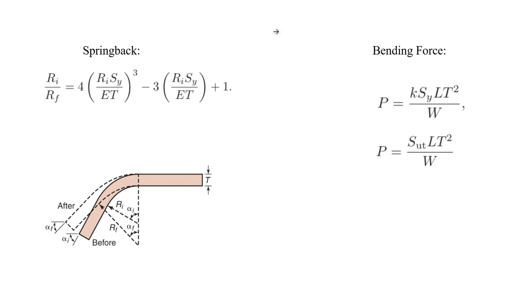The biggest technical challenge in bending is springback. Because metals have elasticity, the part will slightly open up after the load is removed. Engineers compensate for this by using overbending, which means bending the part to a smaller angle than required so that it reaches the correct angle after it springs back.